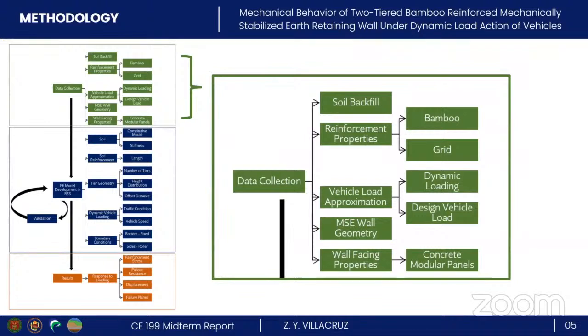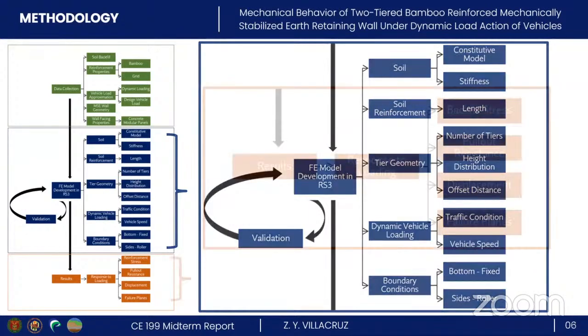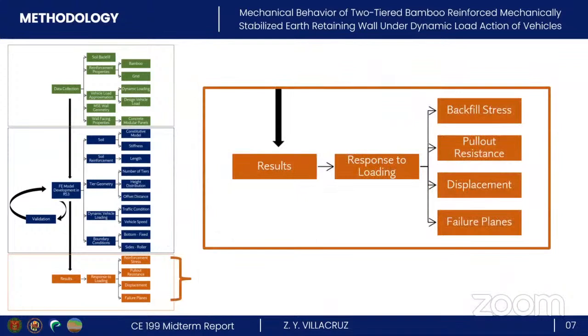The data collection process, which aims to find the appropriate material properties, wall geometry, and vehicle load approximation methods suitable for the application of this study. The finite element model development, which is done in RS3 by Rocscience, where I will be developing my model and adjusting different variables affecting the structure. This will be done after sufficient validation models of relevant literature. This is where my progress currently sits at this time. Lastly, the results of the simulation will include the structure's response to the loading, namely the backfill stresses, pull-out resistance, backfill displacement, and the failure planes of the soil.